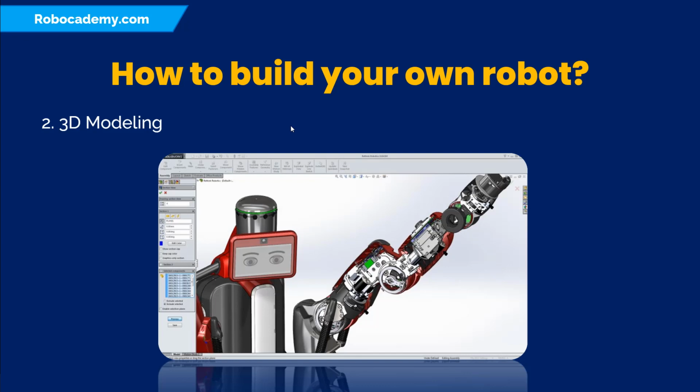So it's like conceptualizing the actual robot. If you model the robot in 3D, you can see how the robot looks. Not only to visualize the robot, but you can assign the kinematics and dynamics parameters of the robot. Kinematics is about the motion, so it will have the links and joints of the robot. Then the dynamics involve the mass, inertia, force, all this stuff. So in the 3D modeling software, you can model all those things. That is the advantage of 3D modeling.